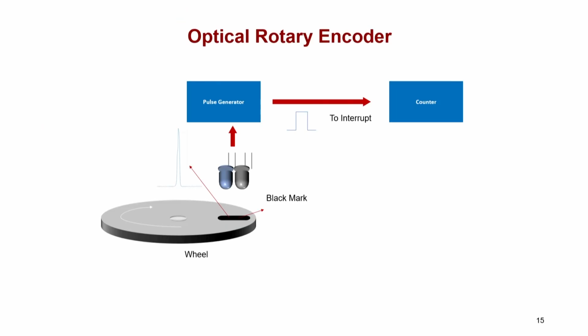How does an encoder work? Well, in this case, what you are doing is creating a kind of pulse generator, and how are you going to do it? You are rotating a wheel like this, and let us say that you are only allowing the current here at this location. So, suppose you have a current source coming like this. Now, when this position is here, then it is opaque, which means it is 0, no current. Only when this slot is coming, the light can emit. So, the optical system, LED or whatever, can actually emit the light. So, the light goes and it creates a spark. So, that is a pulse generator.